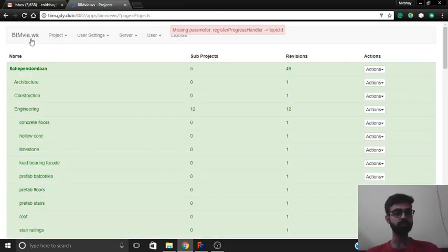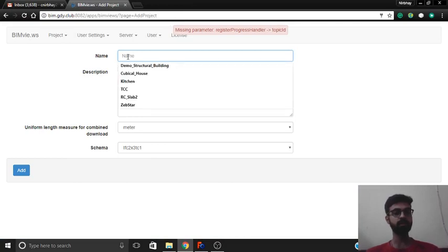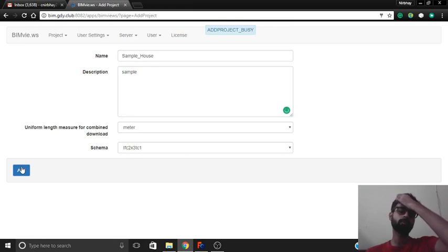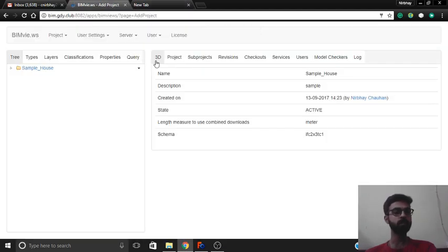So let's do that. We'll create a new project. Let the name be sample house, the description be sample. The dimension is in meters and the schema is IFC2x3. Let's add it. The server is a little busy, I guess. Yeah, so now we have this folder created for sample house.